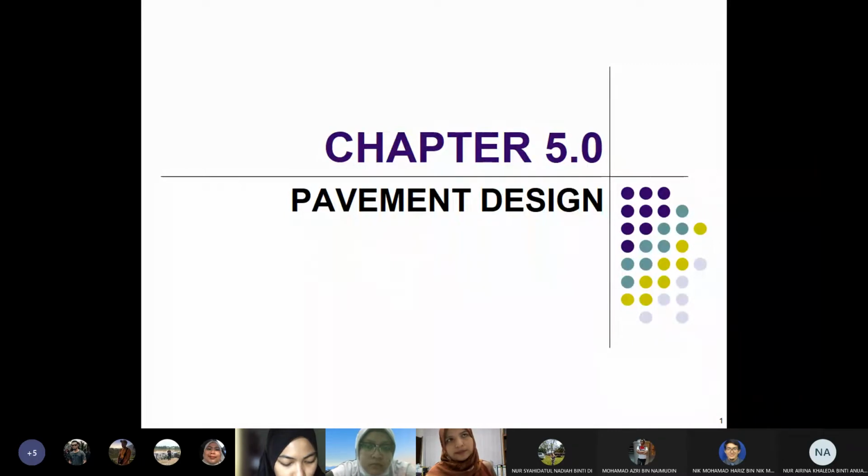OEL 1 is still fresh because we just did it last week and two weeks ago. In OEL 1, one is aggregate testing, where you test impact and also abrasion, and another testing is on the bitumen, where you do your ring and ball test and also penetration test. So these 4 tests will be covered under this chapter 5.